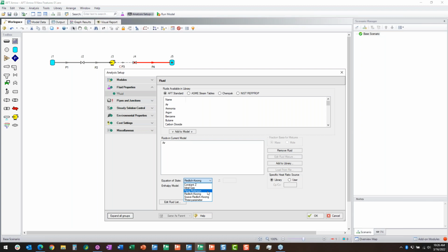They both give very accurate fluid properties. I believe Peng-Robinson was specifically developed for natural gas systems, and it gives slightly better performance around critical conditions. So if you're operating near that point, you may consider using Peng-Robinson, but at the end of the day, Peng-Robinson and SRK are pretty much a tie, but both of them give more accurate properties compared to Redlich-Kwong.